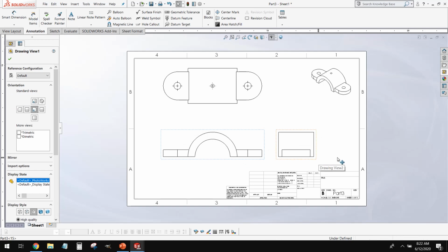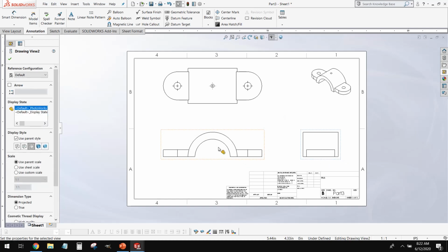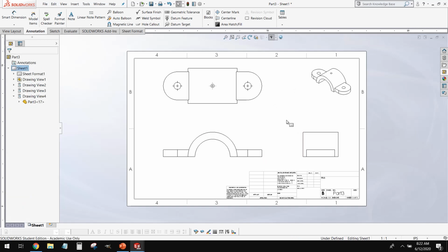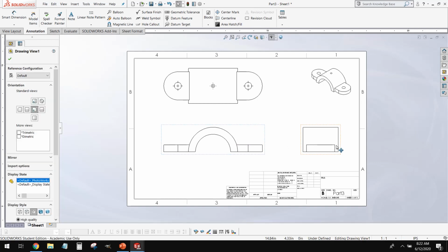Now when we look at our ortho views here, one thing we don't want is to have views that don't serve a purpose. Our standard format is our front view, top view, and right side view. However, we aren't bound to that. We could have just one view, we could have 2 views, standard 3 views. We could add more views. We could have a full set of 6 or so views. So if a view isn't serving a purpose for us, we delete it.